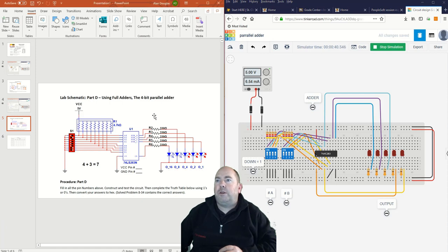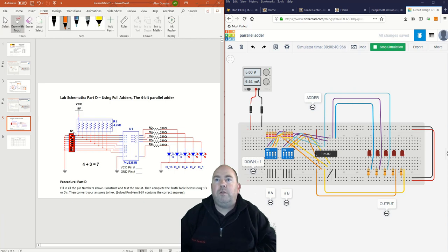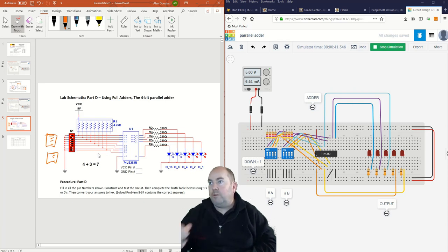So our circuit looks like this. Remember that I have used 2 separate dip switches here instead of the 1 bank of dip switches. Remember that we need to put a resistor and a ground wire on each dip switch that we're using.